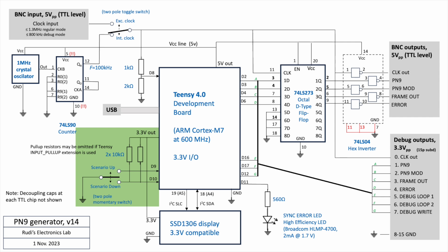I got the well-known SSD1306 display. Probably a lot of you know it. It's this almost 1-inch diagonal small OLED display. One of the reasons, by the way, I'm working with this display a lot now is that you got multiple libraries that all work pretty well. And my experience is that once you got it running with the library on one Arduino, you might find that another Arduino, like the 2040, really does not want to run that library. So at least you can switch to another library and get things going. You have to investigate a new library a little bit and do the same type of things, but you got a bit of flexibility if your display chip has multiple libraries that support it.